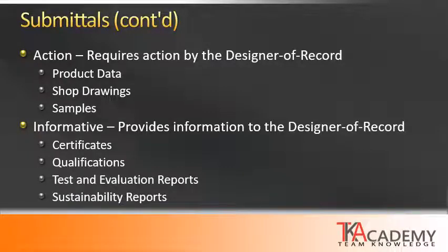The other type of submittals are informative. This just provides information or documentation to the designer of record. This includes certificates, qualifications, test and evaluation reports, and sustainability reports. These are also reviewed by the architect or designer of record, but it does not necessarily designate an action. If there are no issues with these submittals, they are simply accepted and filed as part of the project record documents.